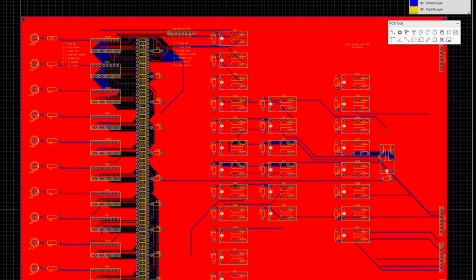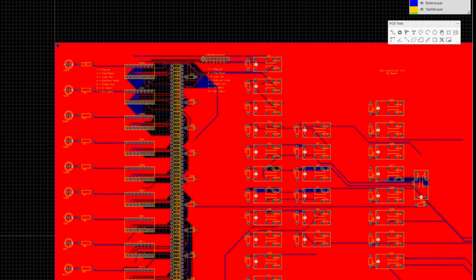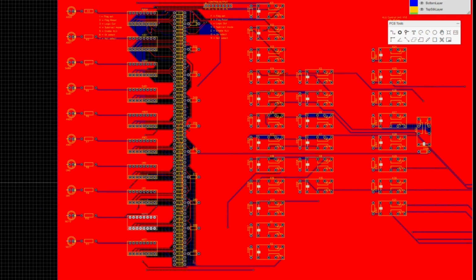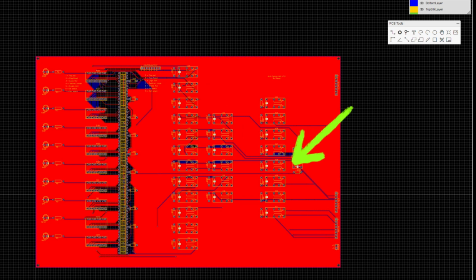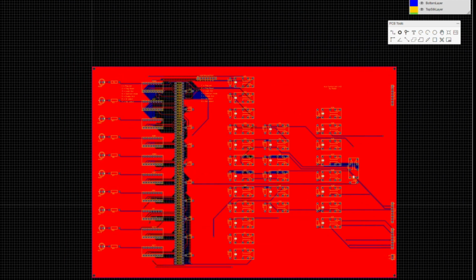But it does require a lot of diodes, because if you have the switches all just connected up to here, it will go around and short itself out to all the other ones. So you need all these diodes along here, so the power can only flow that way and not back through the switches, and then shorting, which is not a good thing. This bit over here is for cutting input B, because input B has to be stopped when doing a NOT operation, otherwise it goes wrong because it doesn't like it if there are 2 inputs in the logic board under a NOT.